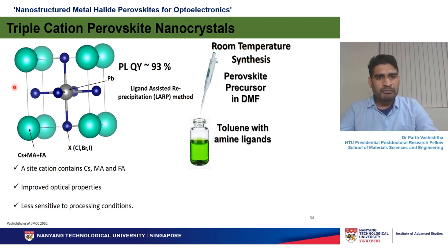So the triple cation perovskites are really good for higher scalability, and they have emission towards 530 nanometer, because cesium lead bromide emission is 518, 520 nanometer. If you want to use this for display technology, for TV screens, the ideal emission we need in the green spectral region is 535. So the closer we are to 535, the better display it will make. And this material does make 530 nanometer emission. And the synthesis of this is much simpler than the other one.